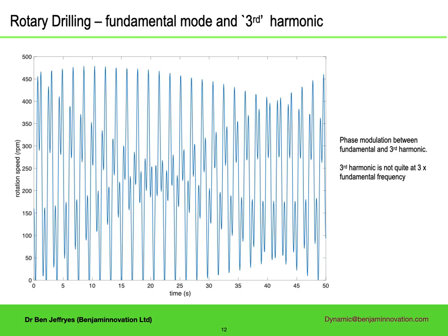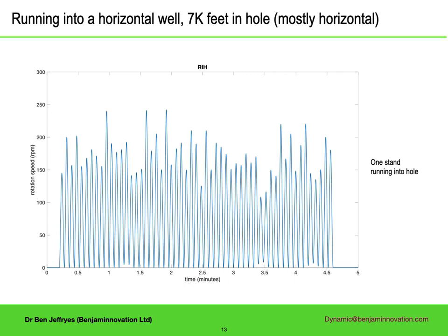But that isn't what always happens. This synthetic graph is based on low-pass filtered data and just shows the low frequencies. You can see that there are two dominant frequencies, which are the bottom two harmonics, one approximately 1/4 wavelength and the other approximately 3/4 wavelength. Because the drill string has a BHA and other structure, the second resonance is not at exactly 3 times the first resonance, which is why you see this interesting peak frequency modulation. This is another illustration of why this stick slip cannot just be coming from bit excitation.